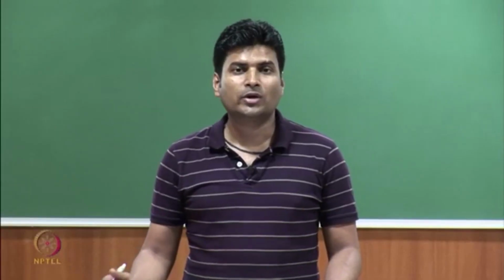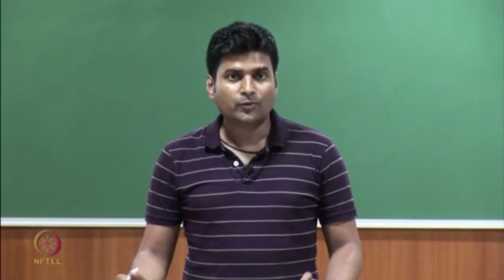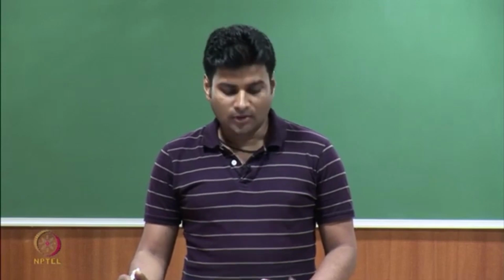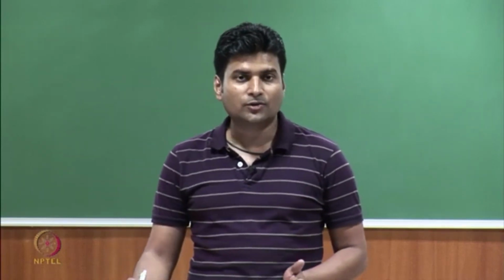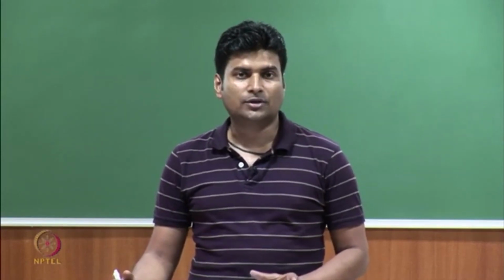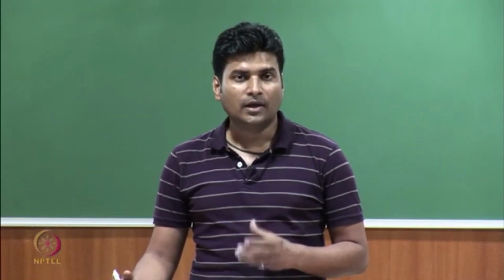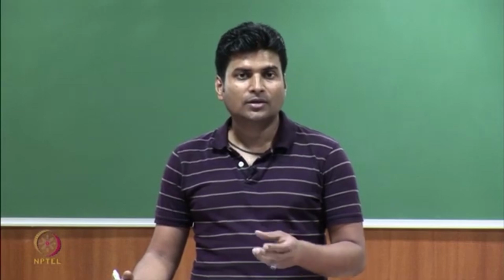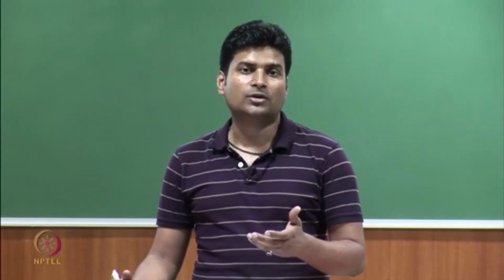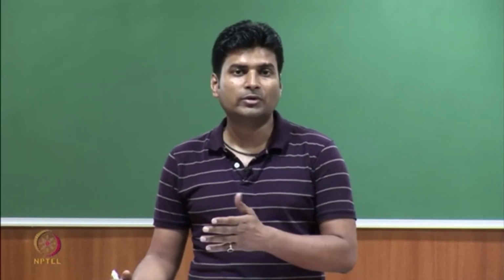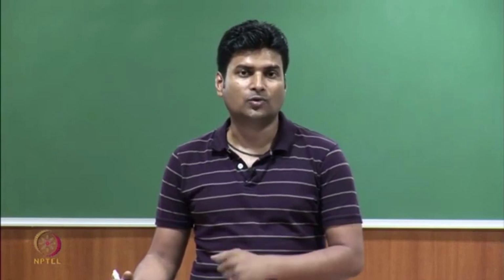Hello everyone, welcome to lecture 19, and in this lecture we are going to discuss the strain matrix in the cylindrical coordinate system. You can recall that in the last two classes we derived the equations of equilibrium in the cylindrical coordinate system, and the idea was to solve the deformation problem in this system. Just as we found stress and its equations in cylindrical coordinates, today we would like to know strain in this coordinate system, and later on we will relate stress with strain in this coordinate system.